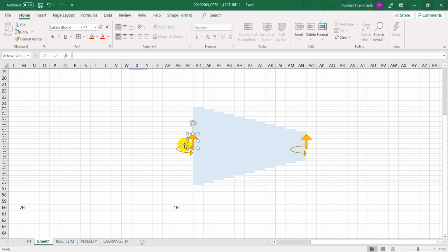These 4 forces and moments are the function of that 1 unit applied displacement at the left end. Is that right? Then you continue. You fix this degree of freedom, you fix this degree of freedom, you fix this one. You apply 1 unit rotation.